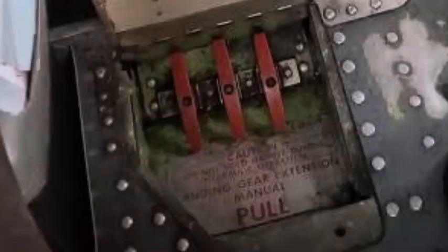In case hydraulic system A is not available during the flight, the nose landing gear is also equipped with a manual extension mechanism or system. So we have three levers attached to a panel on the back side of the first officer seat, and the center lever is for the nose landing gear.